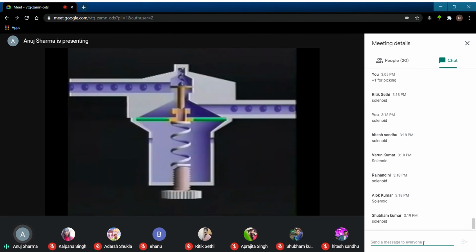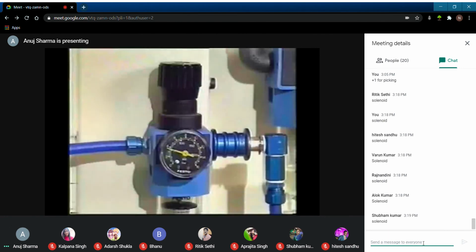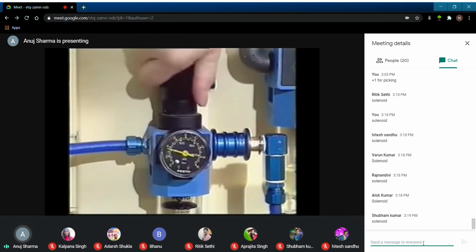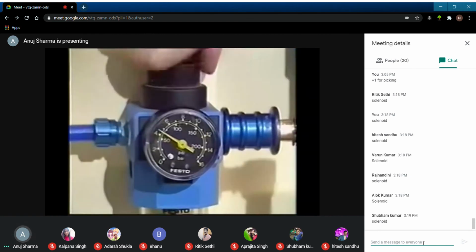One type of pressure valve is the pressure regulator. It's responsible for holding the operating pressure constant by regulating the flow orifice. When the pressure increases, the valve automatically closes partway, reducing the flow to the circuit. The pressure regulator also smooths out pressure spikes from the machine circuit by venting excess pressure through atmosphere. Every service unit contains a pressure regulator.